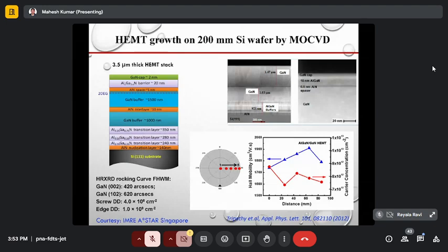So here you can see we have grown around 20 nanometers. We have to grow this material on a foreign substrate, because gallium nitride substrates are not available: when we melt gallium nitride, decomposition of gallium and nitrogen starts before melting. Mostly it is grown on sapphire, but we can even grow on a silicon substrate, and we do stress management because of the lattice mismatch and thermal expansion coefficient mismatch between gallium nitride and silicon.